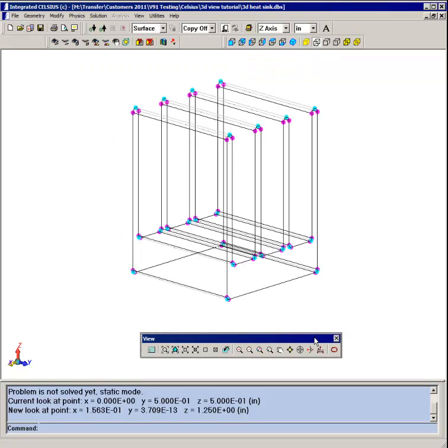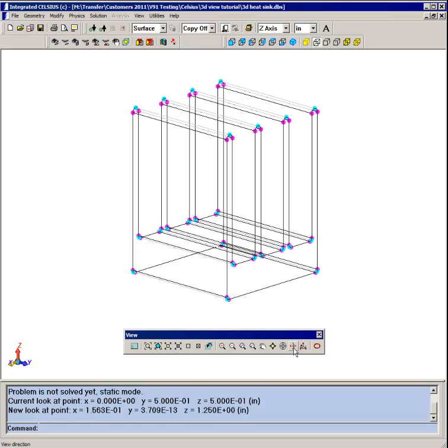I'll show you one last feature about rotation, and that's what's called the view direction. That lets you assign a numerical value, and if you have to, let's say, do some kind of presentation or a screen capture, maybe you've rotated your model to exactly the right view, and you think, well, what if I close the model or rotate it again? Could I ever get back to that viewpoint?